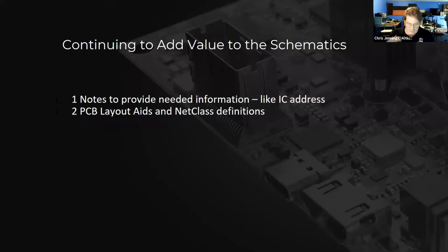And as speeds increased, and as we started putting more and more onto the die so that the chips got more and more complex, the biggest problem that ICs have was getting enough power into the chip and getting it distributed across the chip. And the second level problem, but as significant, was getting the heat out of the chip. And the basic physics say that if you lower the voltage, you can save significantly on the power.